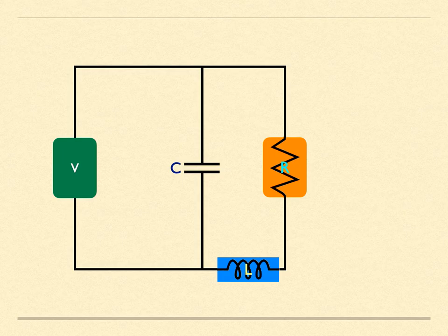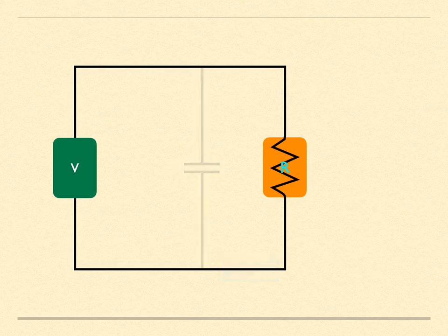In particular, the capacitance and inductance are related to changes in the flow of current around the circuit. Because a lot of our interest involves steady state, and by that I mean not changing current flow situations, we start by ignoring the capacitance and inductance. So we're left with a voltage source and resistance. So what is this green box?